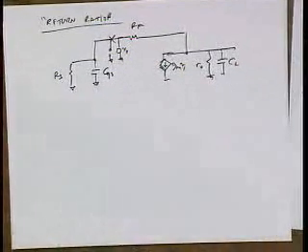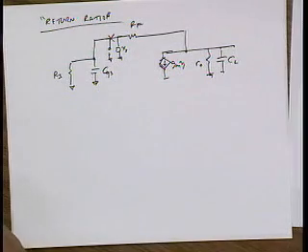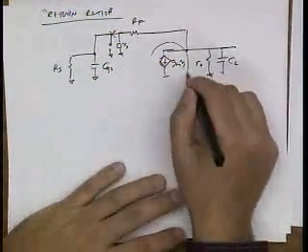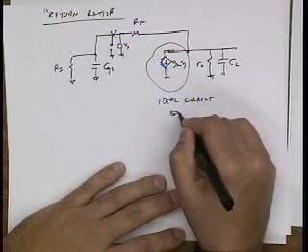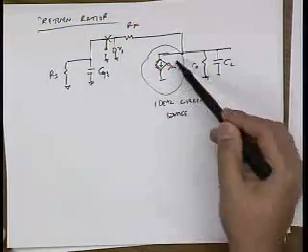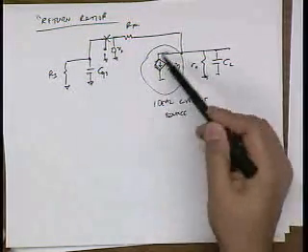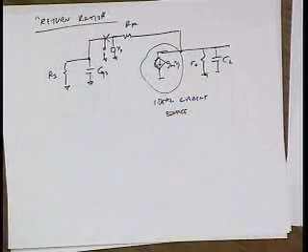Yes? Can we measure loop gain from a different point in the loop, say that current source? Which one? GM VGS. Yeah, right. This is an ideal current source. An ideal current source does not care how you load it, right? So that's the point to break the loop, because you will not disturb anything in the circuit as long as you present the same impedance to the rest of the loop as presented by the current source. So it's ideal. I can just inject the circuit with a current source, and the current source doesn't care, right?